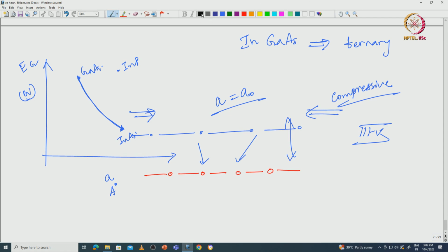Okay, so the fraction of indium that you are using, say I am using 20%, so 0.2, then gallium will naturally be 0.8. So what people write is x, and this is 1 minus x, that is the mole fraction. So x fraction of indium arsenide is mixed with 1 minus x fraction of gallium arsenide, okay,